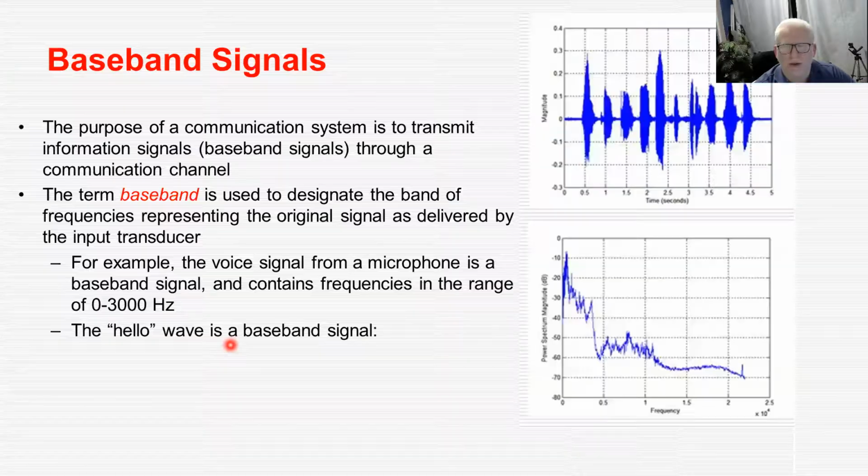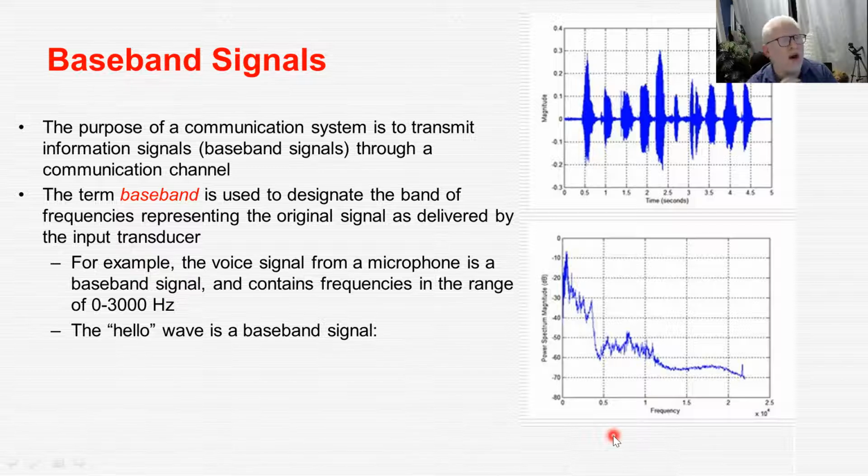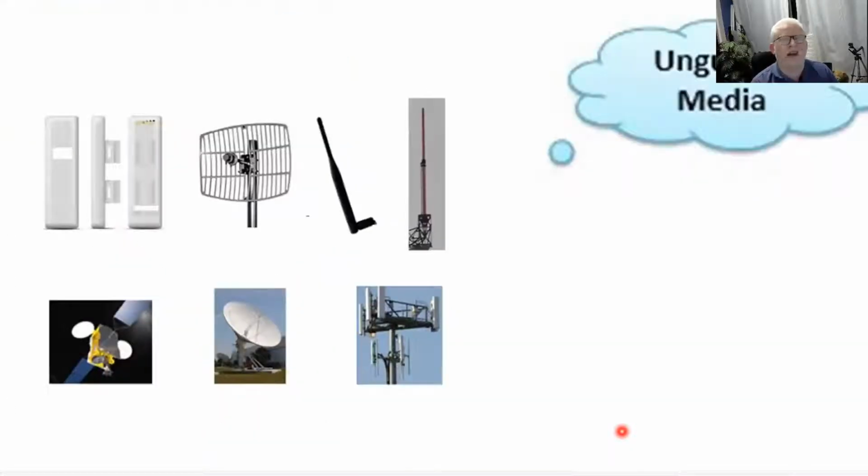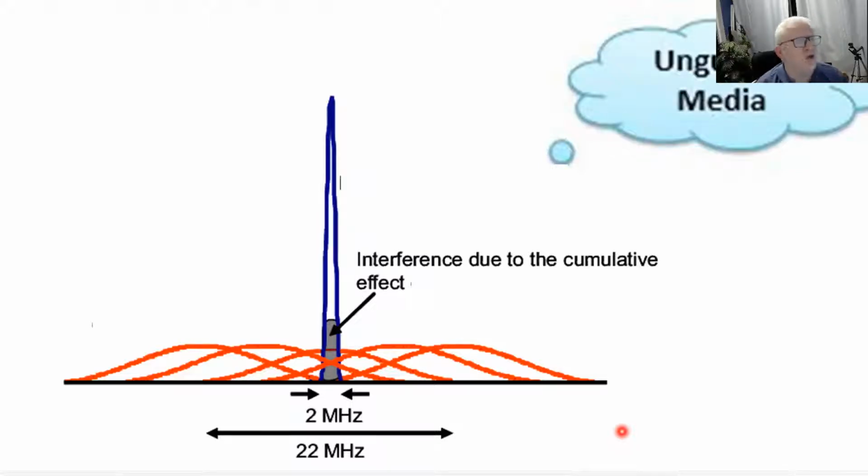What if we are dealing with an unguided medium, and all of us are sending our voice over a channel? All our signals are located on the same frequency spectrum, or the same frequency portion. All our voices or sounds are located within the same band, as we already saw in the first lecture when we did this scanning over the sinusoidal signal. So all our voices are in the same band. What if all of us start to convert our voices into an electronic signal using a mic, and then all of us transmit this over an unguided medium? Simply, what will happen? What's called interference.